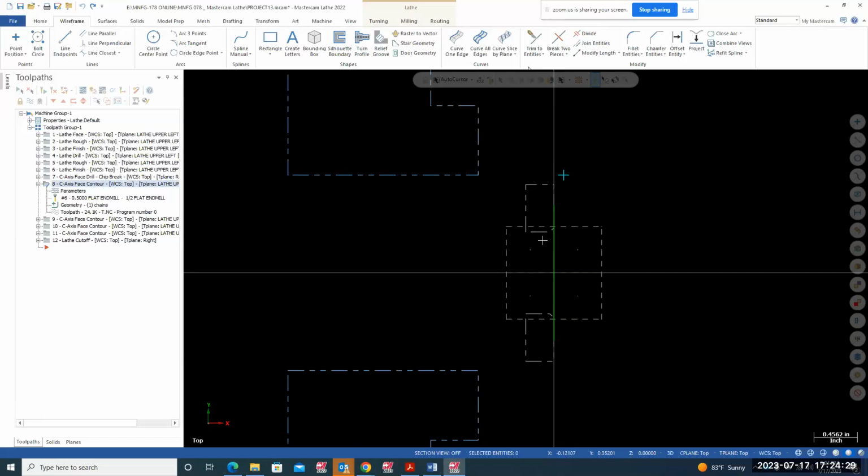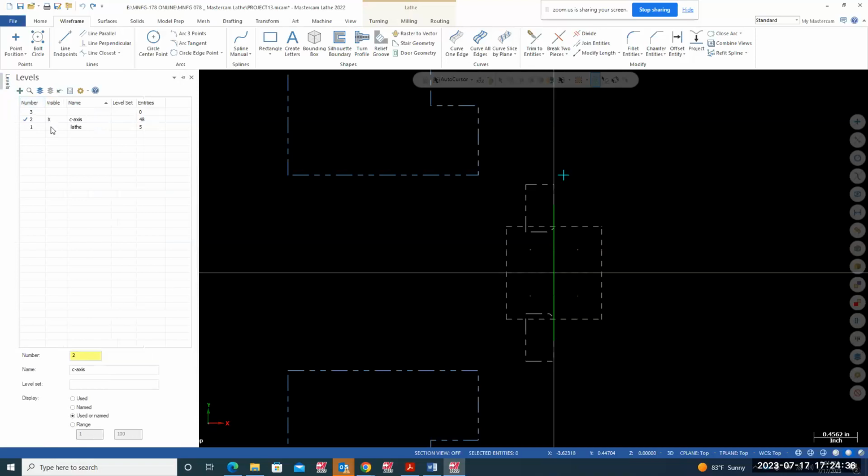But that right there is like the top, isn't it? Yes, this is a top. Okay. So this is a top. We take care of this stuff on the top, just drawing this, cutting this, like the 5 tool path I showed you: face it, OD rough, OD finish, drill and bore. That takes care of the top part. That's your regular lathe operations: face it, OD rough turn, OD finish turn, drill it and bore it.